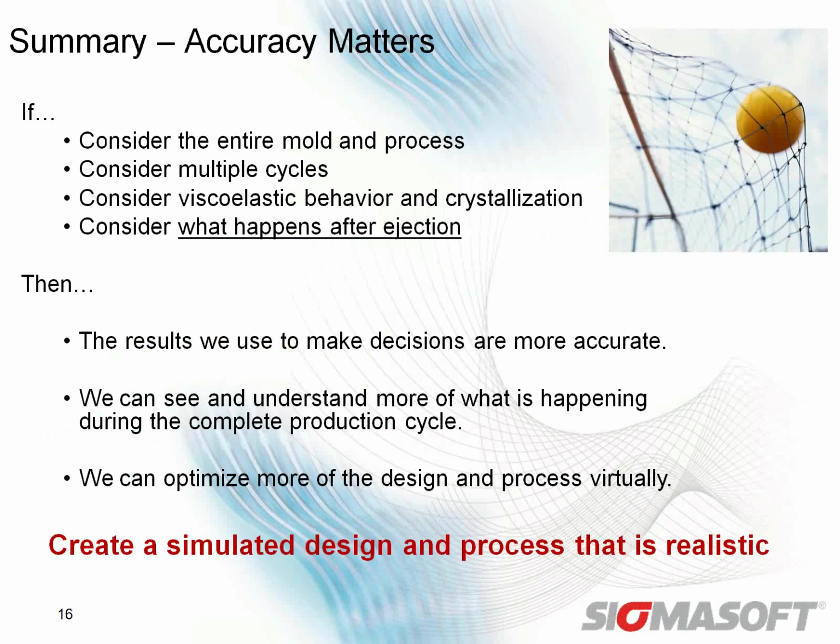Okay, so in summary, if we consider the entire mold in the process, this is talking about some of the things we've already talked about in some of our webinars. With SIGMASOFT, we just get closer to reality. We allow you to consider all the mold components, the entire process, multiple cycles, the viscoelastic behavior of the material, and the crystallization that occurs. And then what we talked about today, what happens after ejection. By doing all of these things that people in the simulation world are typically not used to doing, we get a much closer snapshot of reality.